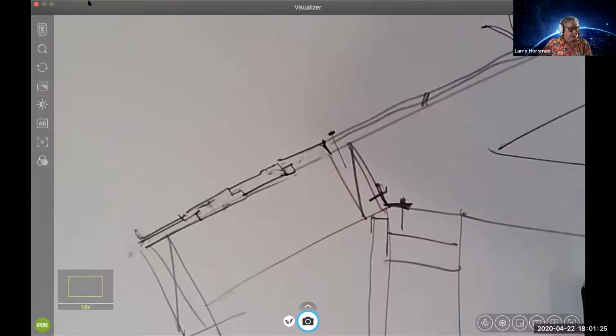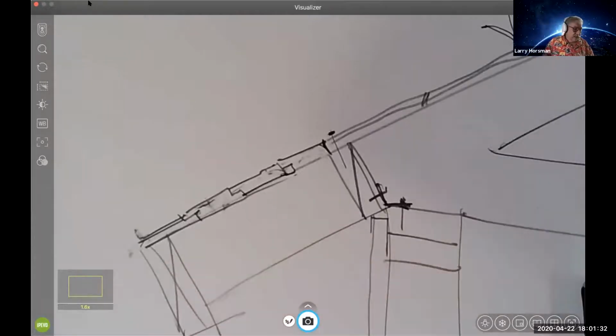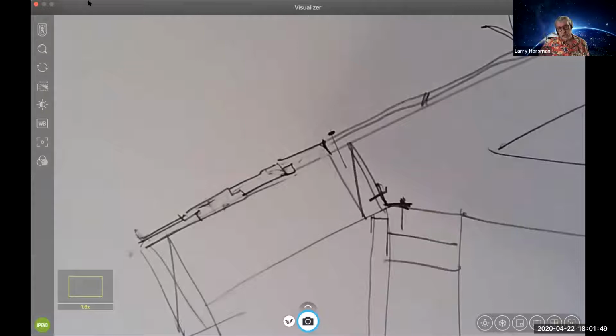So they used to use just a 1x6 or 1x4 T&G or a shiplap on the outside. The thickness was close enough that it matched the roof sheathing, the 1/2-inch roof sheathing. The problem always was they would run the shiplap up above that block. And when they run the shiplap up above that block, you don't have shear transfer from the roof diaphragm. So some details you'll see will look like this.